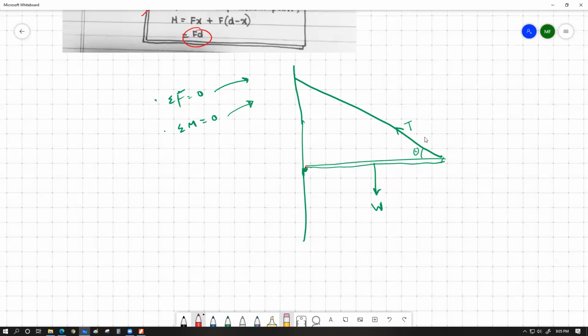And how can we find out the direction of this force? I'm not talking about magnitude. Magnitude can be calculated by a set of formulas. I'm going to show you the formula as well, no big deal. But to find the possible alignment of this force, we can simply find the cross point of the two forces that we have available. For example, W and T are going to cross at this point, which means the reaction force at this location of the plank should have its line of alignment go through that point as well. So this is how the reaction force should look.